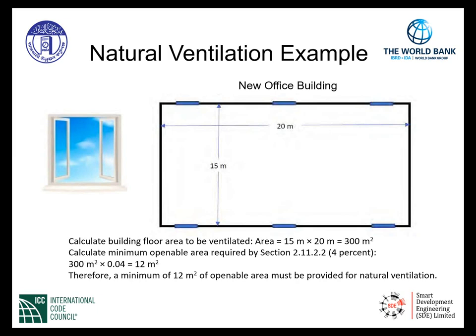Now, when this method is provided, the authority must review the plans and make sure that the minimum openable area complies with the code. As inspectors out in the field or on the job site, we need to verify that the openings have been placed in their proper locations according to the approved construction documents, and verify that the opening area is compliant with the design and this code.